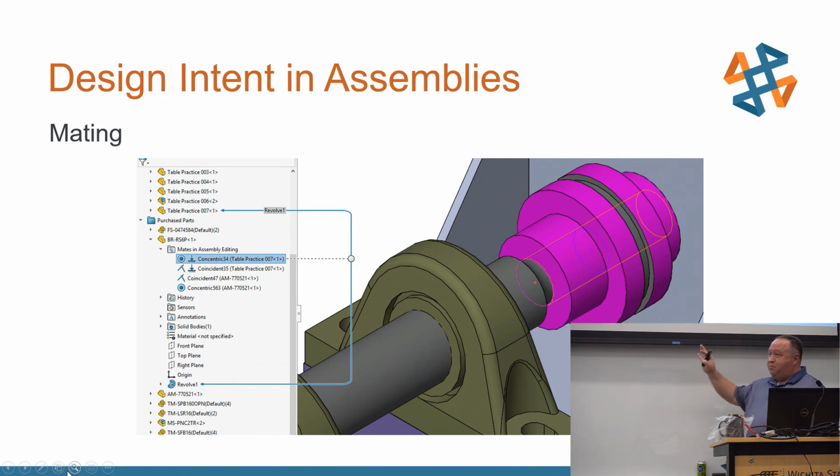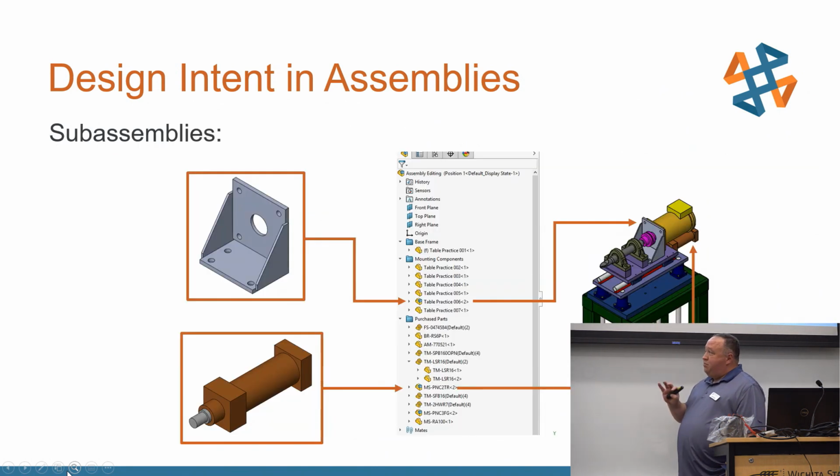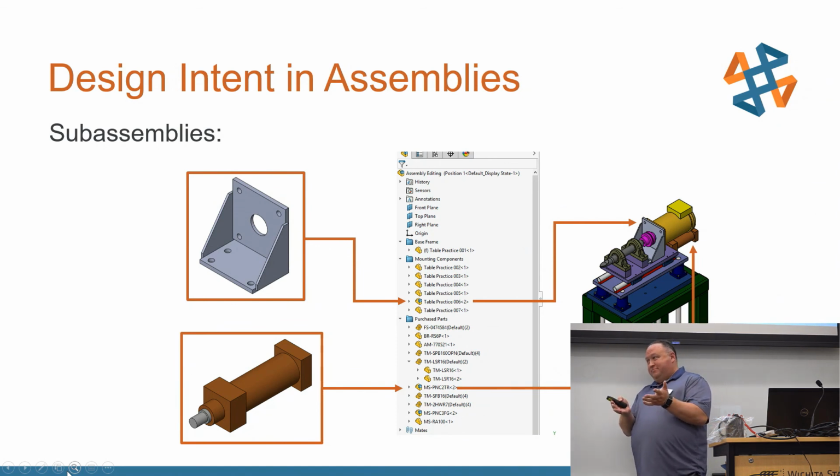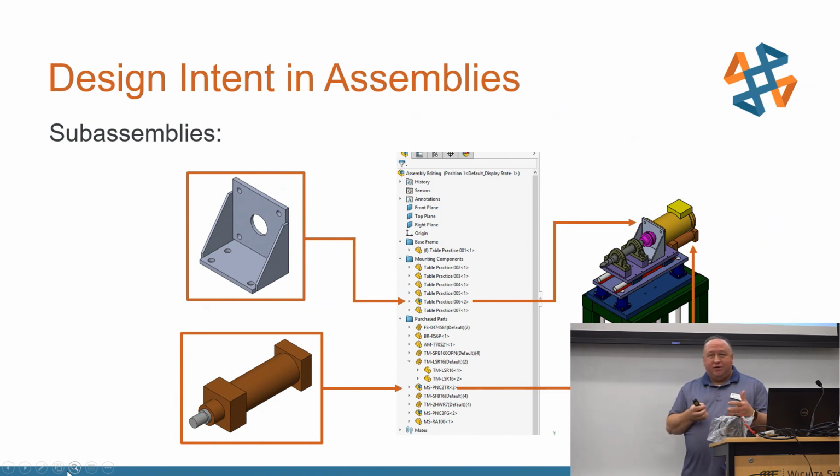Another one, this is such a simple fact: when you build assemblies, build them just like production is going to build them. There's your subassembly. If they put these 6 parts together, make those 6 parts a subassembly. It's not rocket science. It's super easy to follow. Okay.